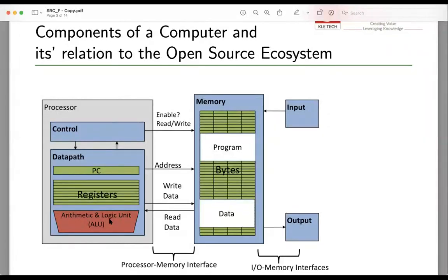And we study this, and then we use processors which are available in the market, right? So we use processors like Intel, AMD, or Apple Mac. Now you have got M1, right? So the idea is that we know that a processor comprises these things, right? It has a program counter. We know why a program counter is required. We know that there are various registers. These are treated as memory locations, which are to be used by the processor internally. And then you have the arithmetic and logic unit. And then obviously to control all that, you have a control unit. So this is the whole design of a processor.